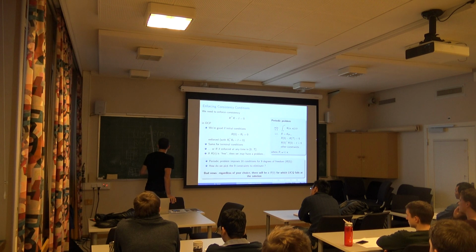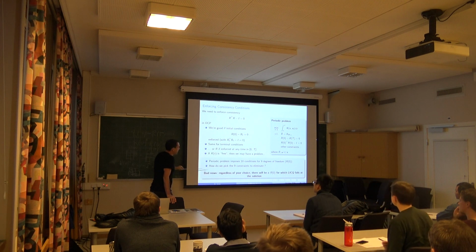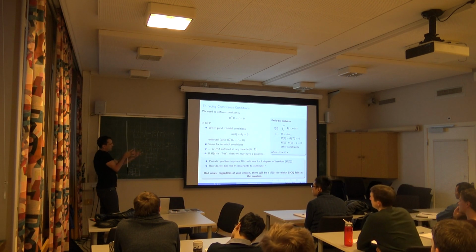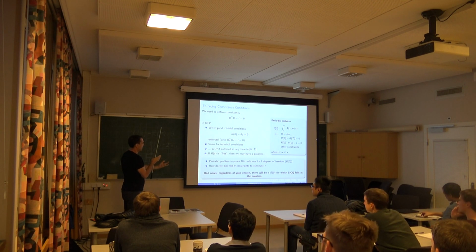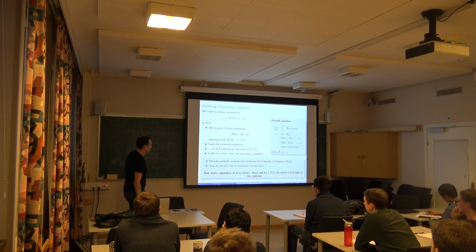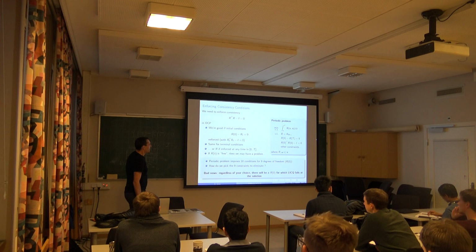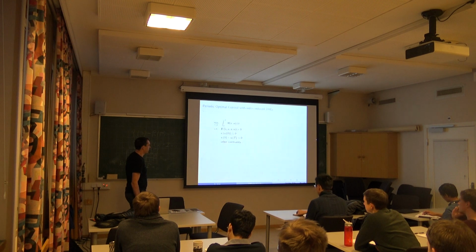Once you eliminate your constraints, you would have 9 degrees of freedom for 9 constraints, but you may still end up in a problem. The system may turn in a way that makes 2 constraints linearly dependent again, and then your solver will suffer from that. This stuff is not really obvious, and it actually took us a while to fully understand these questions.